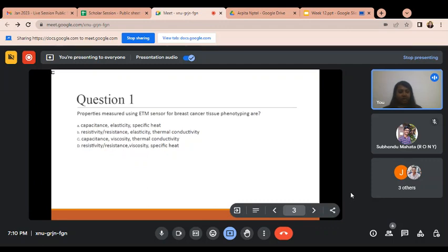What is the need to dip the wafer into DI water? If directly after dipping into the piranha solution we dry the wafer, then some particles of this solution can remain on the wafer surface.